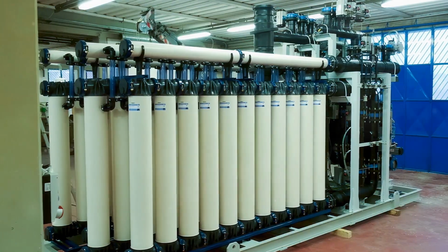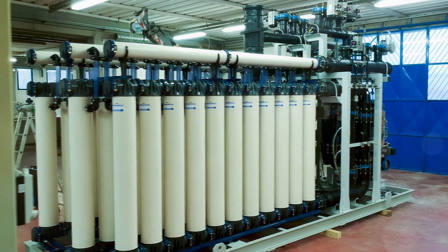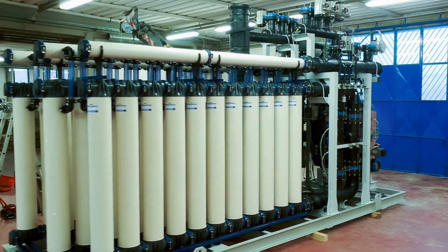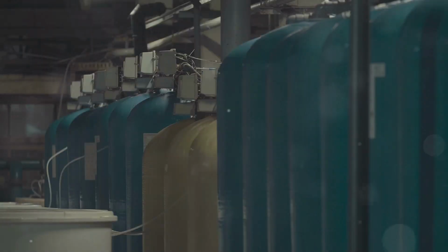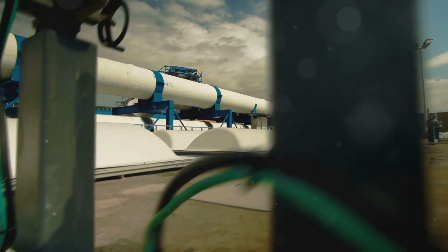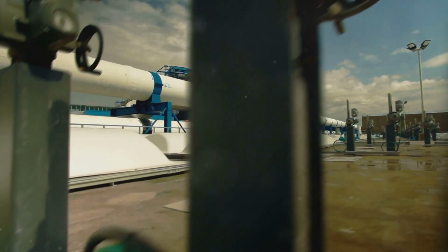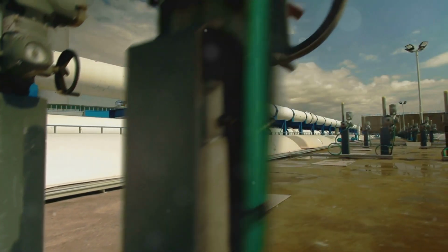Membrane separations, microfiltration, removing particles in the range of 0.1 to 10 micrometers. Ultrafiltration, separating macromolecules and colloids in the range of 0.01 to 0.1 micrometers. Nanofiltration, separating particles in the range of 1 to 10 nanometers. Reverse osmosis, removing ions and small molecules by forcing a solvent through a semi-permeable membrane.